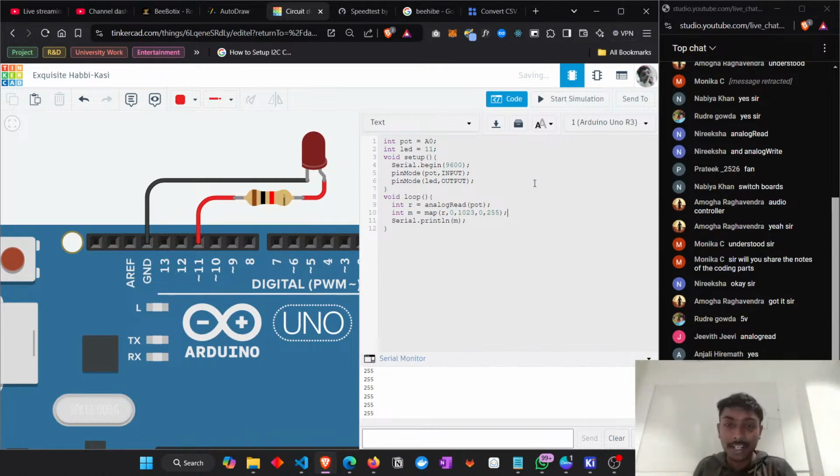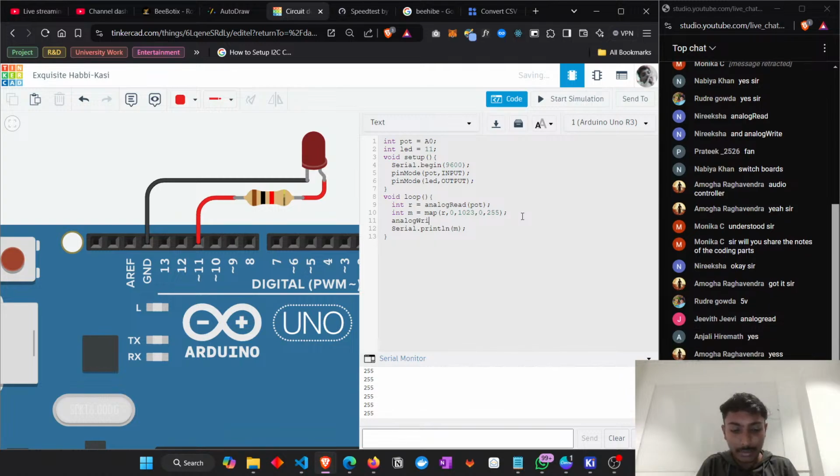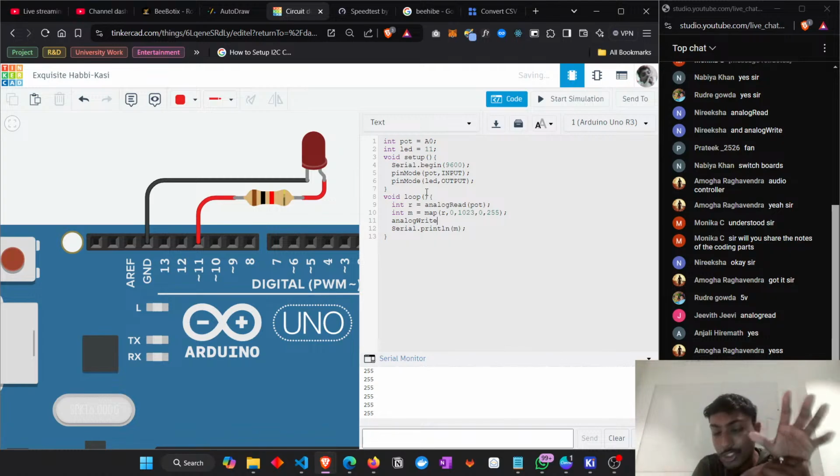You're correct. analogWrite. Now, what I will do, I will try to change the pattern of this, right? Now, I will write analogWrite. Yeah, analogWrite, Manoj, not analogRead. It's analogWrite because you are writing the thing, right? Getting my point? You have read already. What is the potentiometer value you have read and stored into R value. Then you are trying to map it. As we saw that potentiometer was giving from 0 to 1023. You have changed it to 0 to 255, which Arduino can understand properly and generate.